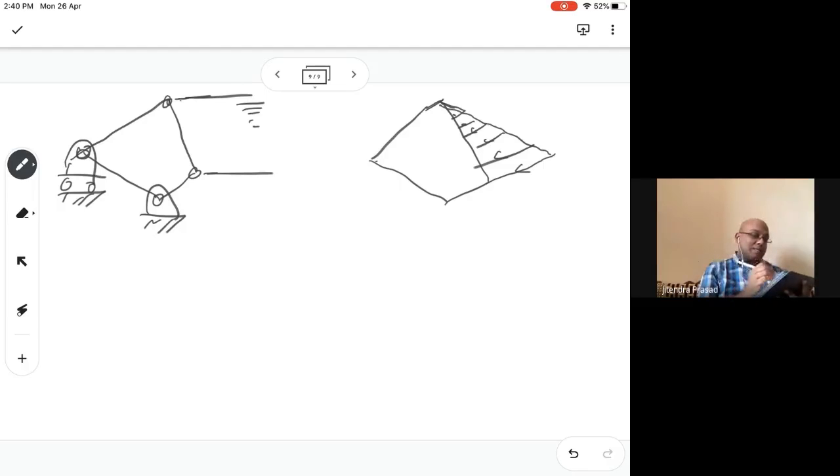Pressure will be, say, it depends on the height, basically x. So from here, let's say this is what we measure. From here it is h, and the pressure P is equal to rho gh, right? So it depends on h only. So h equal to 0, no pressure. H equal to more, it will have more pressure like this one. Okay, then how to find out what will be the force in that case? That's the thing, right?